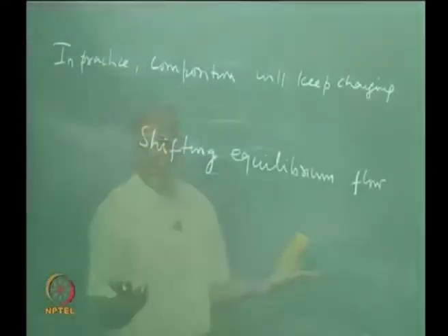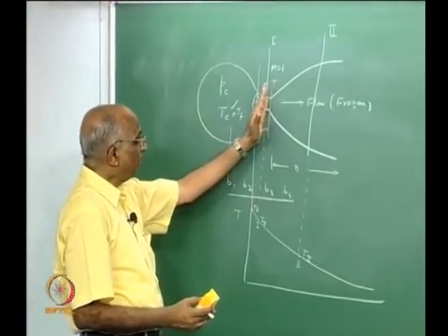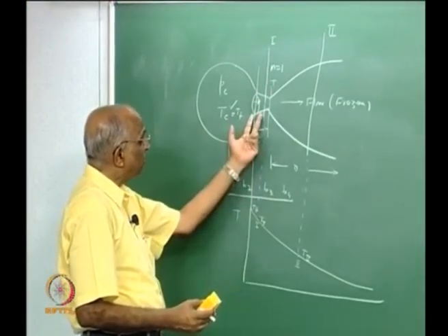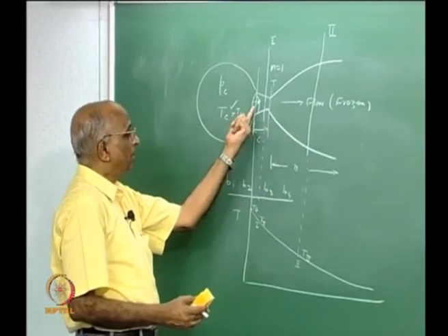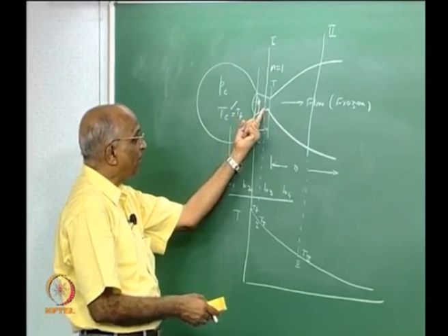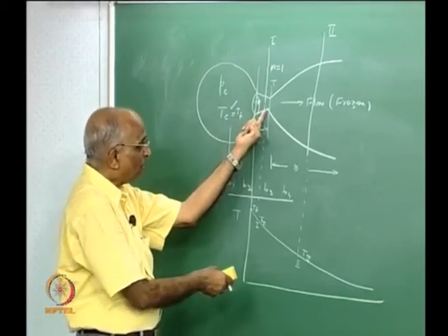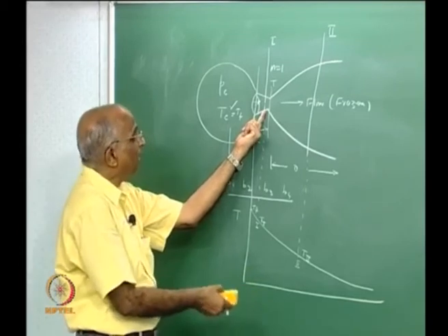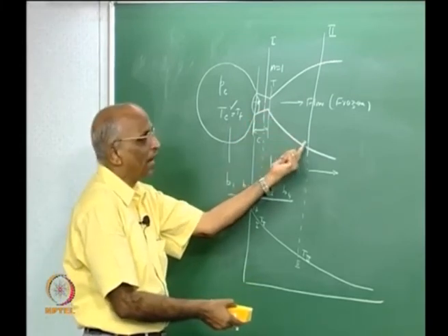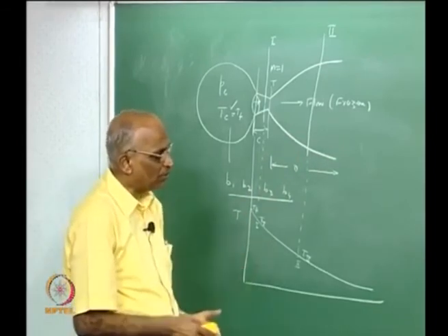Well, to solve this is extremely simple. I go to the next section, I find out what will be the temperature for this particular expansion, assuming the values of gamma corresponding to the earlier section. At this point I find out the values of the new species, I can calculate and revise the temperature again, revise the products again, and so on. I can do this using a chemical, or let us say a shifting equilibrium, calculation.